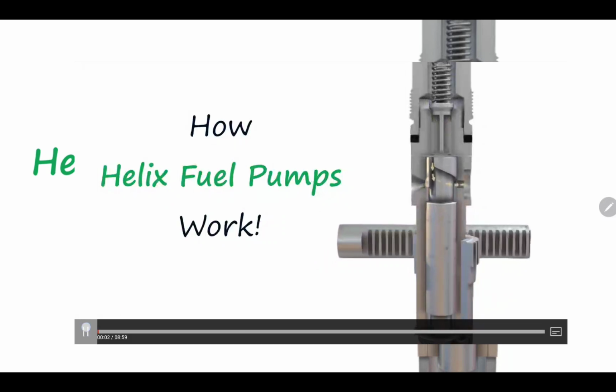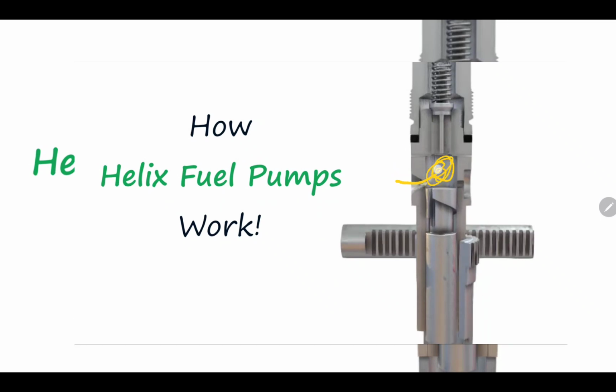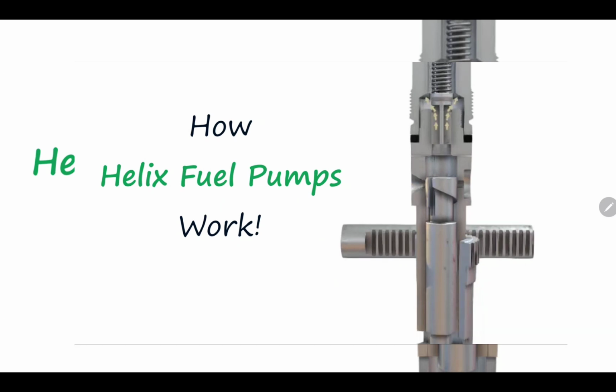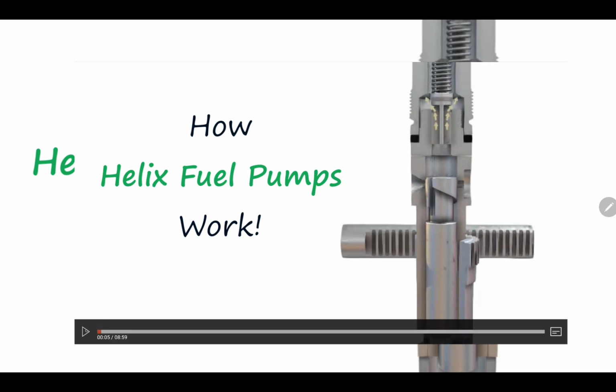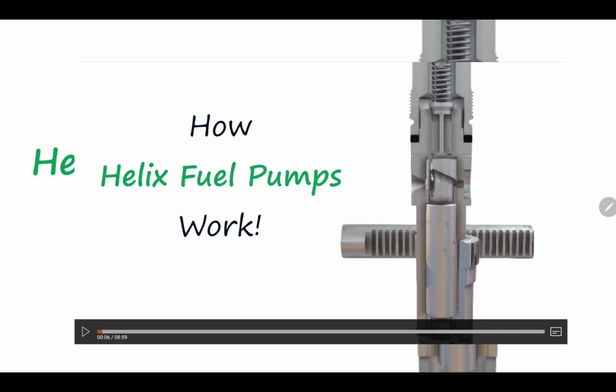You see, if I rotate the plunger like this, when it goes down, the fuel enters and fills the barrel. Okay? And when it goes up again, now it closes both the inlet and the return ports, and it moves up. You see the rotation of the plunger. What did it do? It delayed the opening of the return port.